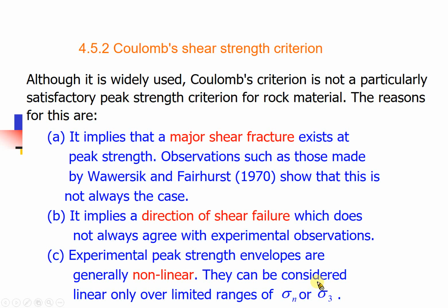Can you distinguish this? Okay? I hope you still remember the JRC-JCS model. The JRC-JCS model takes all of the assumptions of the Mohr-Coulomb failure criterion. You will have the specific failure plane because it will be the discontinuity, right? Specific failure plane. And the failure is caused by shear stress. So this will be the assumption for the Mohr-Coulomb failure criterion, and the JRC-JCS model takes both assumptions.